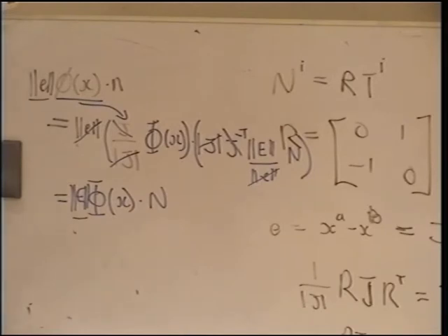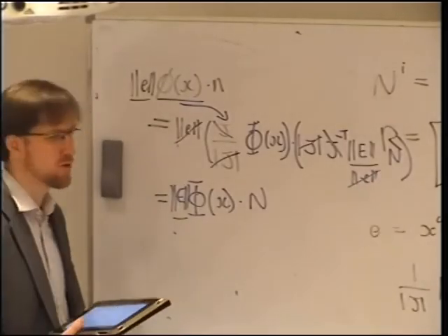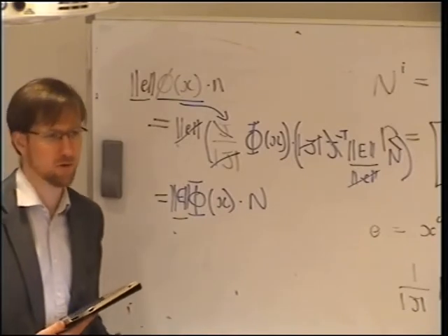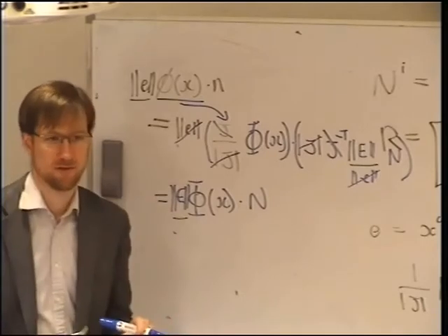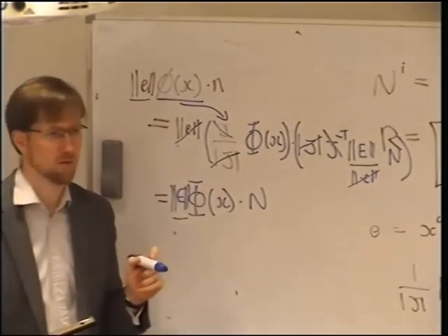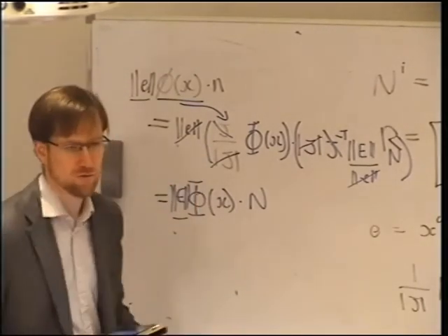And there is a trap here, right? There's a reason why we're tracking around the edge length here, because you might think, well, it's just the reference space, so I can just define it away. And you can just define it away depending on how you want to define your local coordinates and do your local triangle. But using the local triangle that we normally use, that's not the same on all sides. Because it's a normal right-angled triangle, it's got two sides of length 1 and one side of length root 2. So that is not quite trivial.